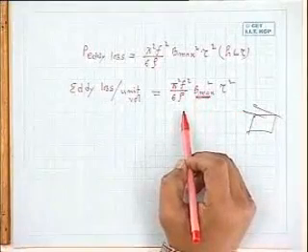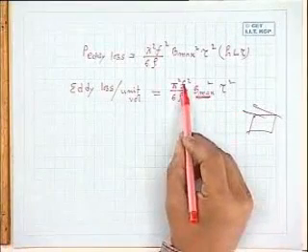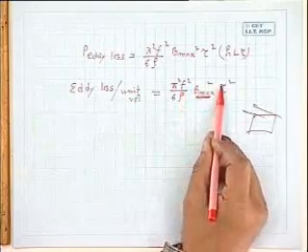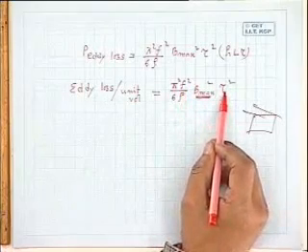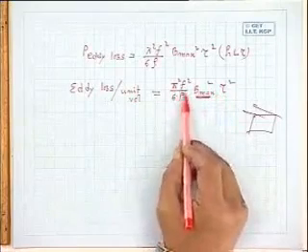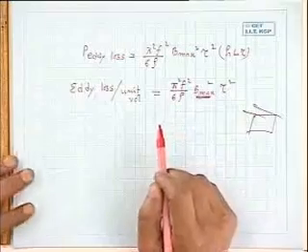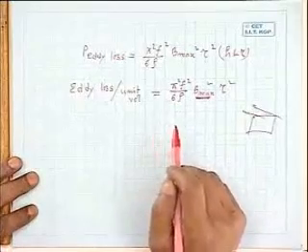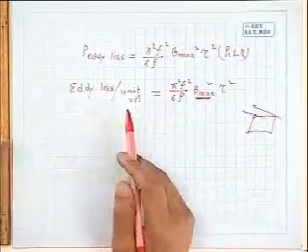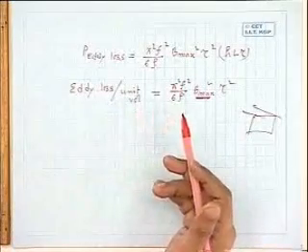So it is like this. Per unit volume it will be like this. So it depends upon the square of the maximum value of the flux density. It depends upon the square of the supply frequency. And it depends upon the thickness square at that low level of thickness. And also it depends upon the resistivity of the material which is used to construct the core.